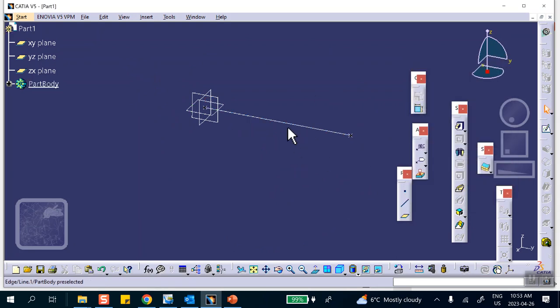And because this is going to be meshed with a beam element, and it has to be done, there is no other way to the best of my knowledge, you're not going to use this beam element as a beam, but in order to be able to specify the stiffness of the spring and things like that, you need to mesh this with an element. It doesn't have to be beam, but this is a line, so we're going to use beam element.